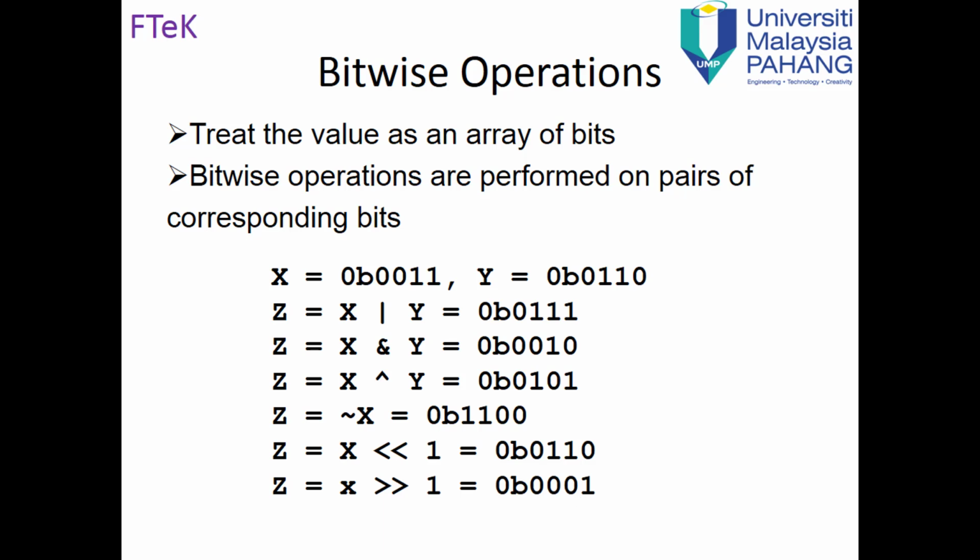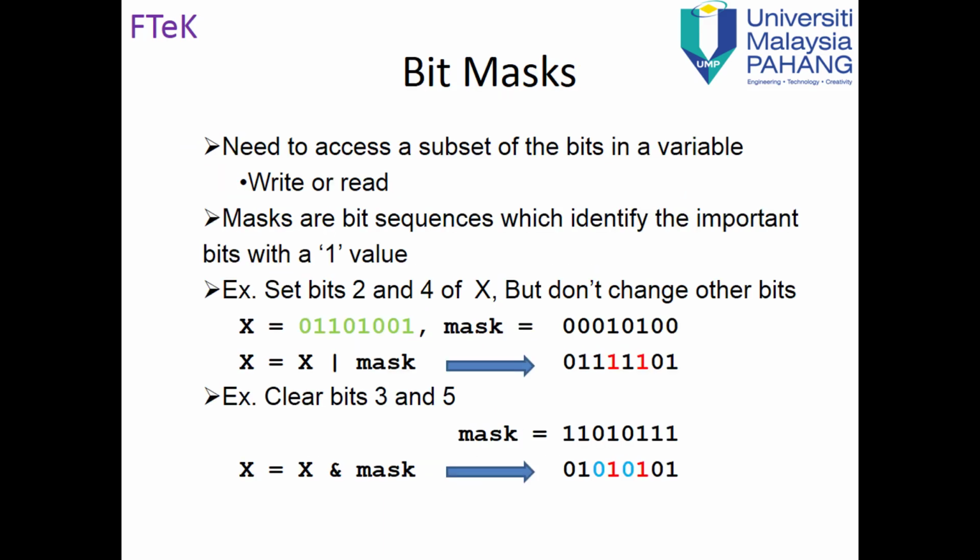Bitwise operations are actually important for one very important technique called bit masking. Bit masking is used if you want to keep some bits without change in one byte. So you have a byte, for example, the register which is connected to port B. You want to change the pin PB2 only and keep the others as they are, so you mask it with OR. I will show one example for setting and one example for resetting or clearing.